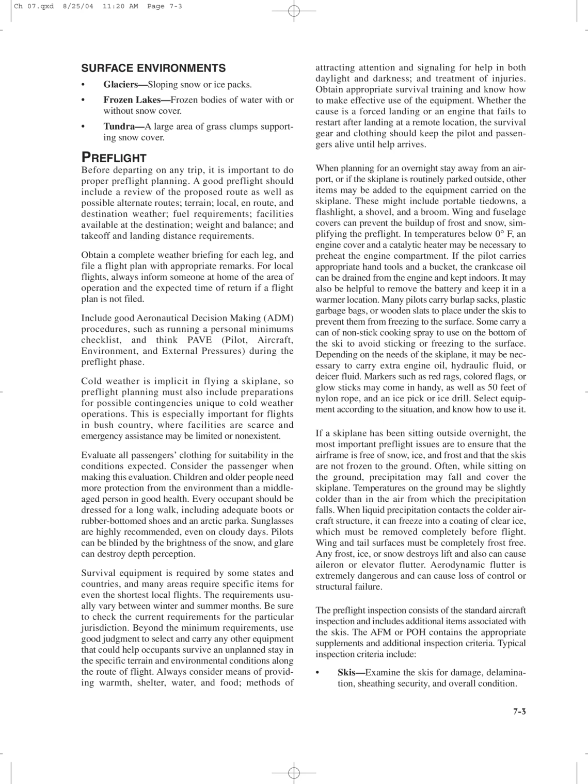Always consider means of providing warmth, shelter, water, and food, methods of attracting attention and signaling for help in both daylight and darkness, and treatment of injuries. Obtain appropriate survival training and know how to make effective use of the equipment. Whether the cause is a forced landing or an engine that fails to restart after landing at a remote location, the survival gear and clothing should keep the pilot and passengers alive until help arrives.